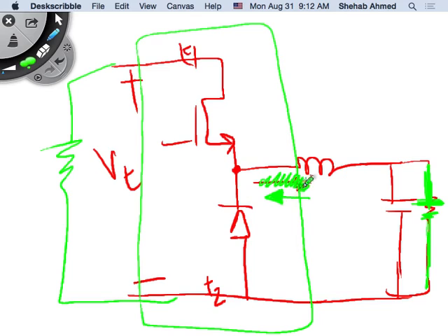No. Why not? Because the MOSFET up there can't backfeed. Exactly. So current has to flow in this direction in the MOSFET, and current has to flow in this direction in the diode, right? So if the current's coming from my battery into this node, it's not going to find a place to flow, right? So this device selection was wrong for this application. For the previous application, it was perfectly fine.